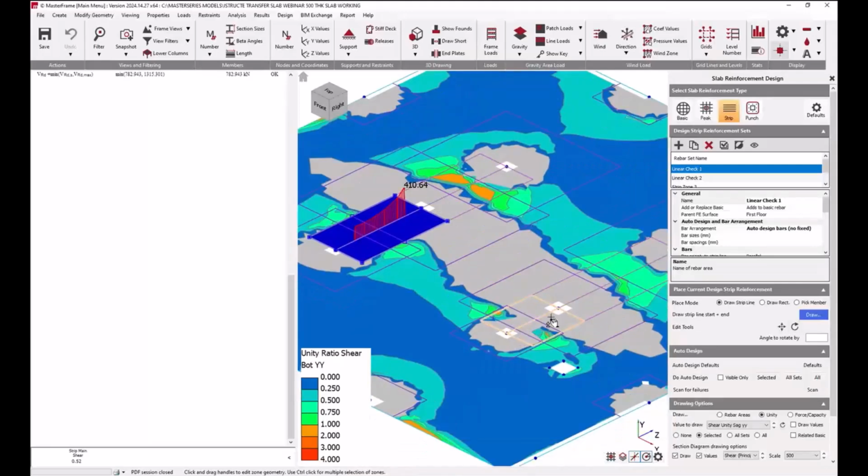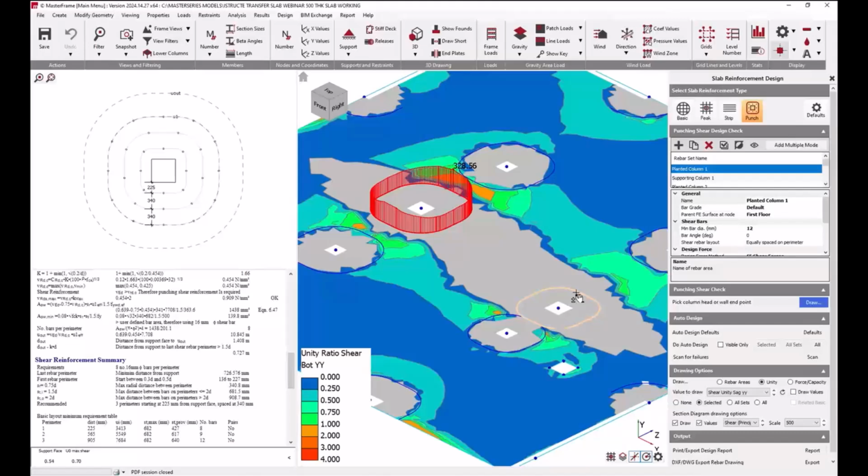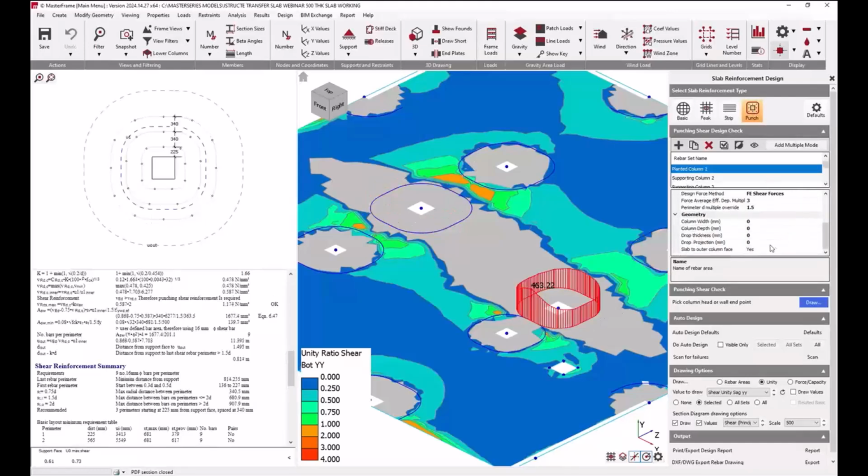Now, over on this face, we've moved the column in a bit, so we've reduced our distance down. So instead of being over 4D, we've reduced it to within 4D, so it's actually at 3D, the spacing between column faces. And as I say, that allows us to amend or override and then change our average to 3D and specify that D value to 1.5.